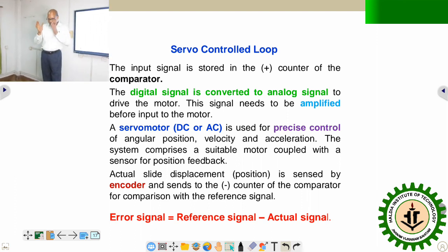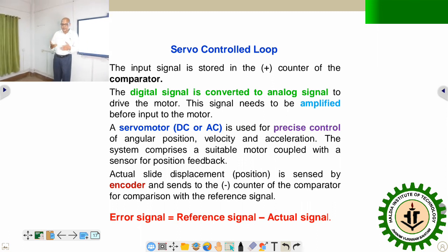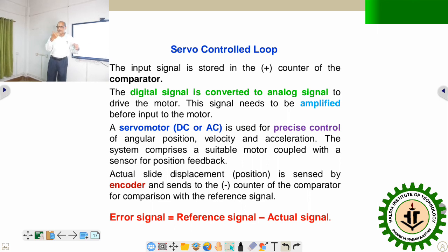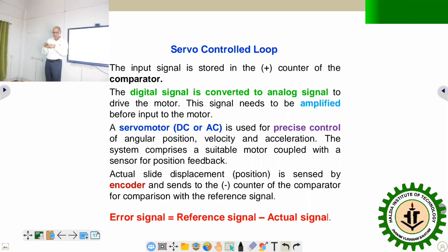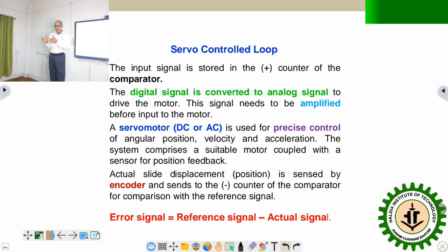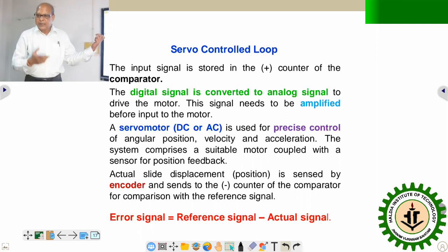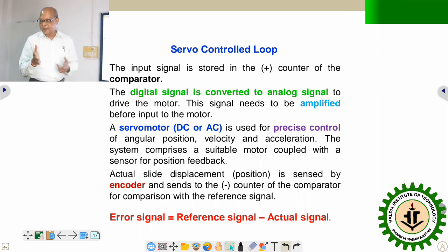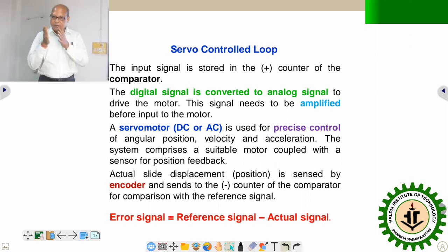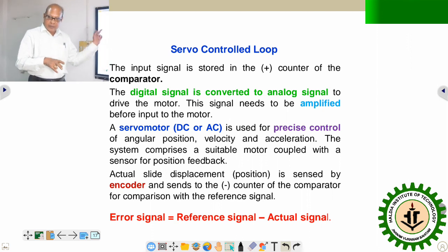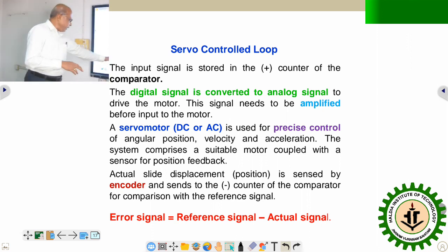Now it is required that during implementation it has to be monitored continuously, so that eventually this 50 millimeter displacement is achieved, and while moving it would maintain the defined velocity or the speed of 0.2 millimeter per revolution. So there are two parameters, one is displacement Z minus 50 and another is velocity feed, which is expressed in millimeter per revolution. If you multiply it by RPM, you will get in millimeter per minute. So velocity has to be measured along with position. So both are two different parameters to be measured by two different categories of sensors.